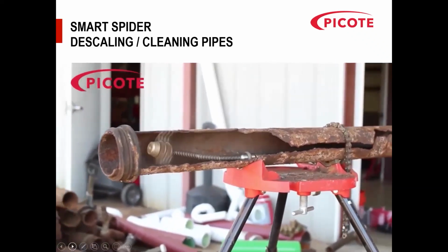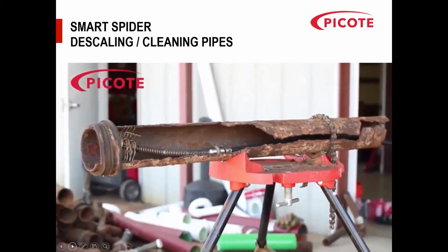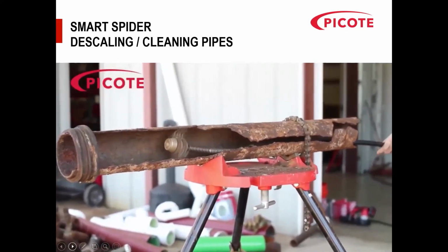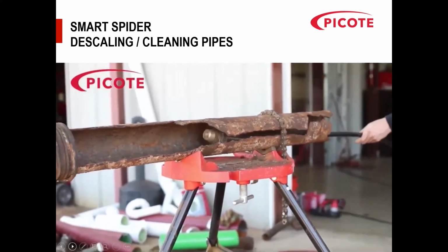The beauty about our machine is we've got the legs on there, and it goes through. You can see the outer casing behind. If you put your CCTV camera and tape it onto the back of that, you can go through, descale the pipe, clean the pipe, and also do a full camera survey. So we have contractors who just use the Spider to get cameras through sections where you can't get cameras or jetting machines through.